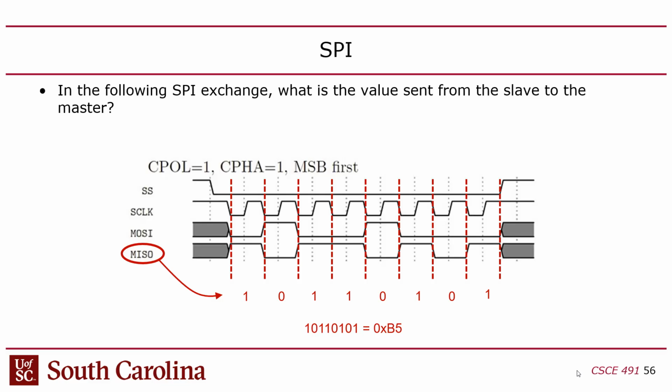Now, notice that I have these dotted lines on the timing diagram. Those are just placed every clock cycle, but they don't necessarily mean anything. They're just a way to line things up on a timing diagram. In this case, they happen to be lined up on the clock edge where we're sampling the data. So I added another set of dotted lines that bracket that.